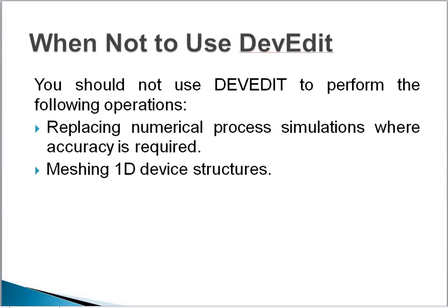When not to use DevEdit, you should not use DevEdit to perform the following operations: replacing numerical process simulations where accuracy is required, and meshing 1D device structures. We cannot use DevEdit for 1D device structures.